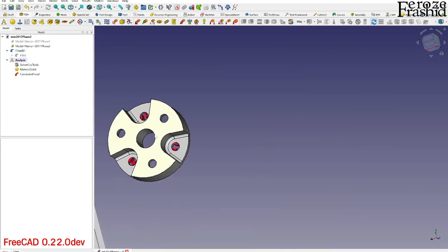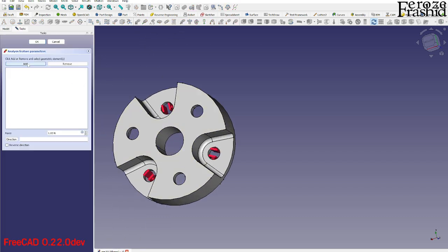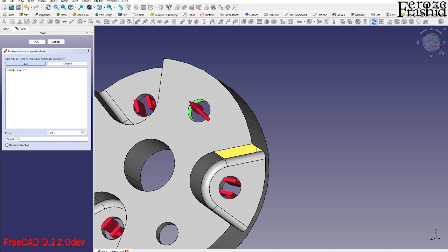and this will have the loads. So we are applying 800 Newton load. Okay, so it should be vertical, and I'm gonna go ahead and unclick that add and select one of the vertical edges and direction.